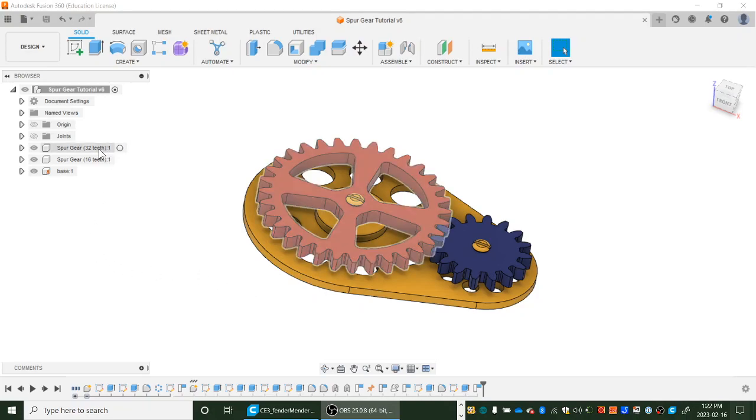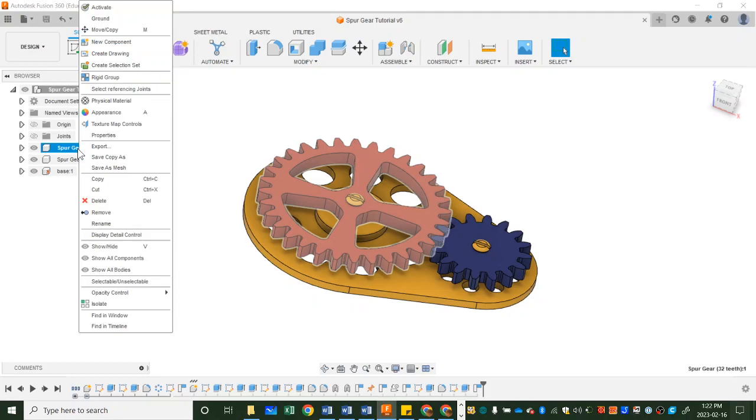We're familiar with all sorts of file formats. This one might be new to you, but follow along and it'll work out. So over here we have our different parts that we'd like to 3D print. And for each one of these, we need to create a printing file. So it's a 3D model file. And what you're going to do is right-click on the actual component, and you're going to choose Save as Mesh